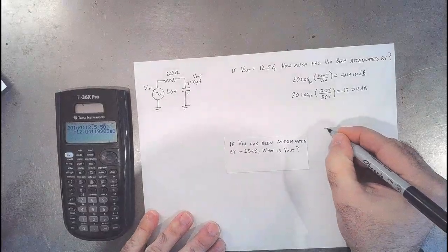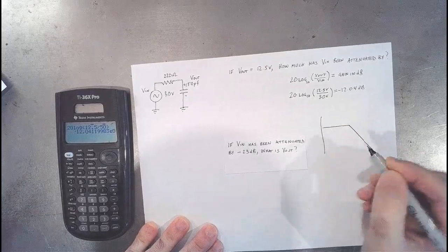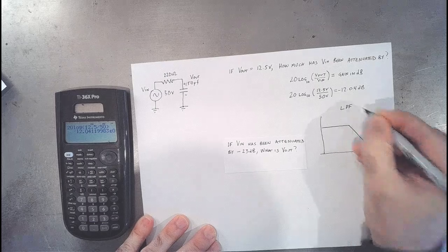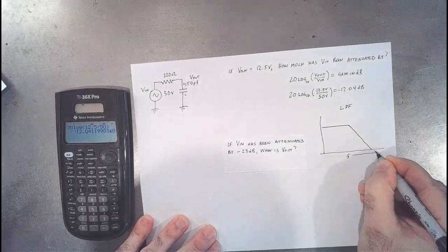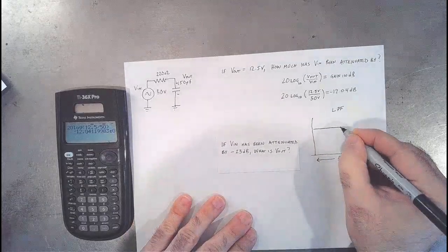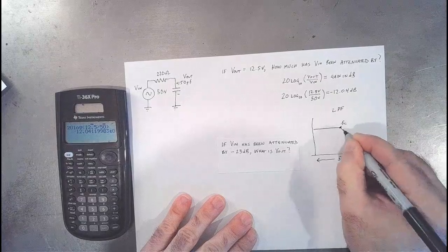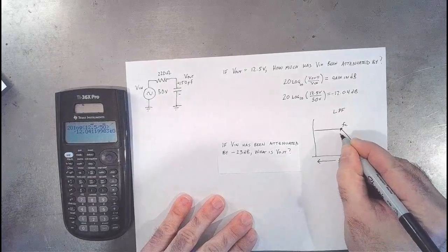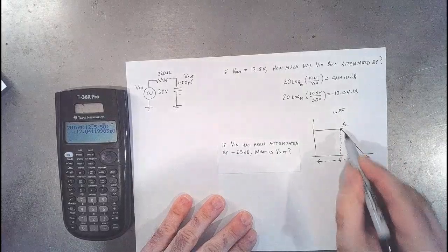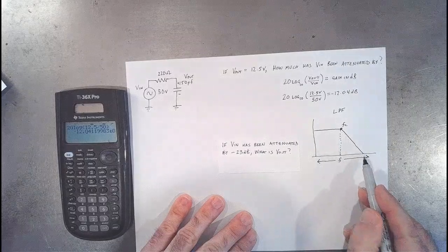And if we look at the Bode plot of this filter, it looks like this. So along this axis right here, this is frequency. This spot right here is the critical frequency of this filter. That is where it starts cutting things off. In this case, this is a low pass filter, so you can see that when you hit this frequency right here, it's going to start rolling off high frequencies.